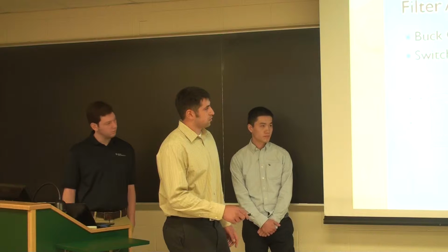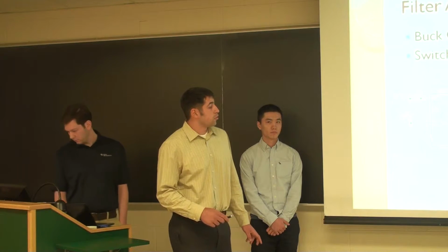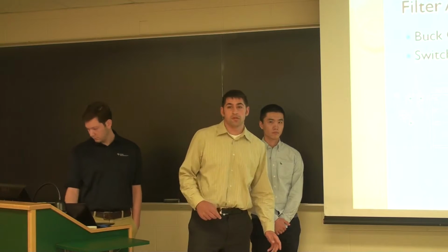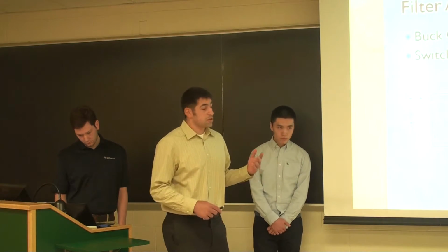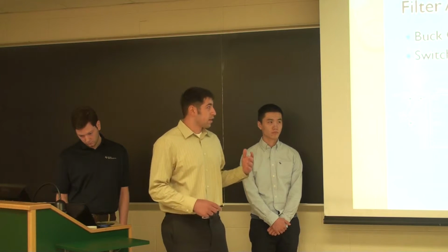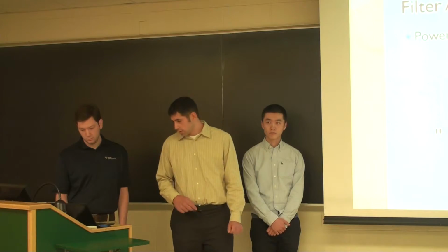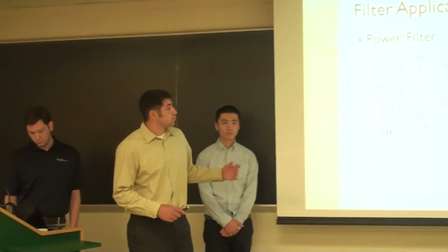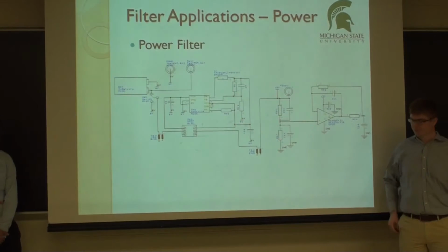As you can see by this graph over here, the noise ranges from microvolts to millivolts, and in some applications that can be very significant, including ours, which is measuring ECG signals. So that could significantly affect our circuit. And then to solve this noise problem, we decided to implement a low-pass filter.